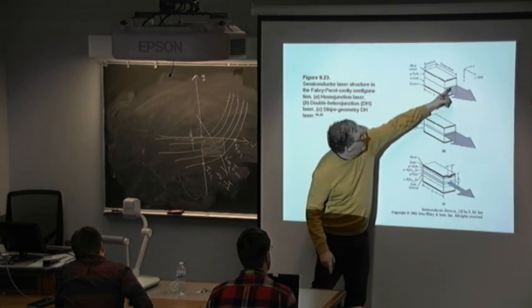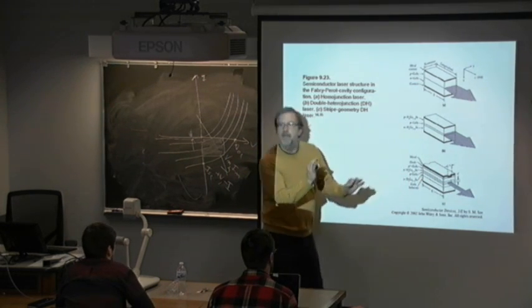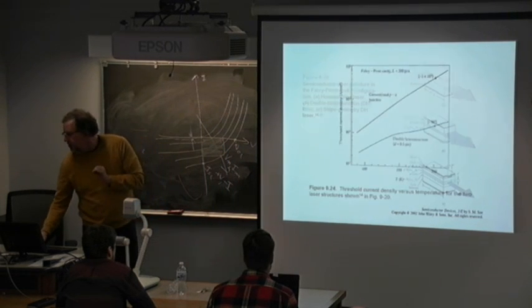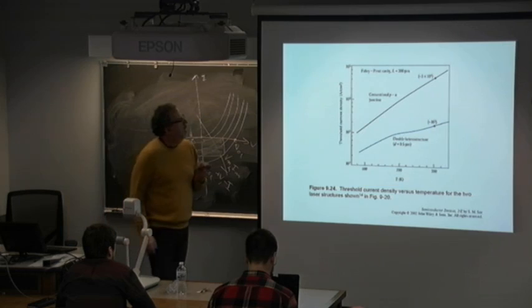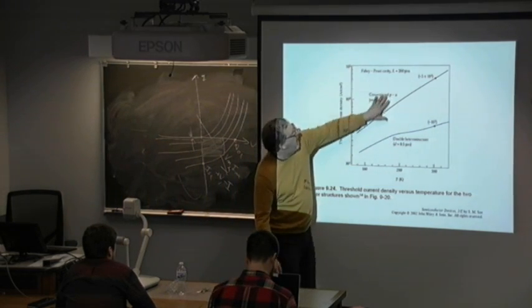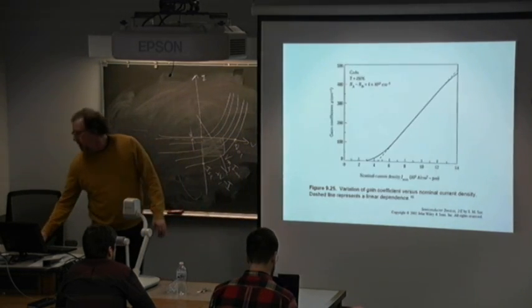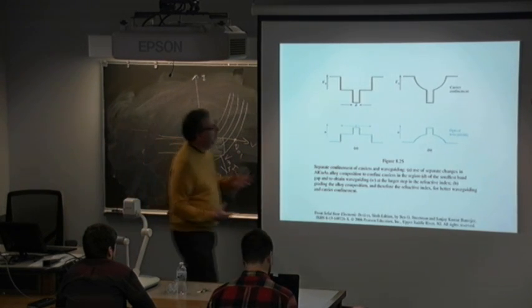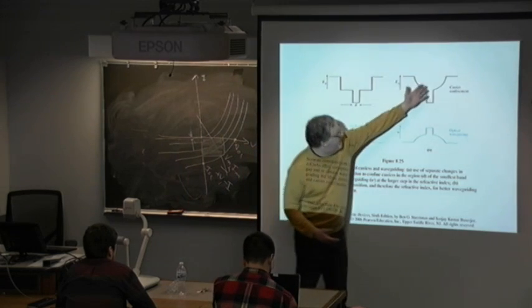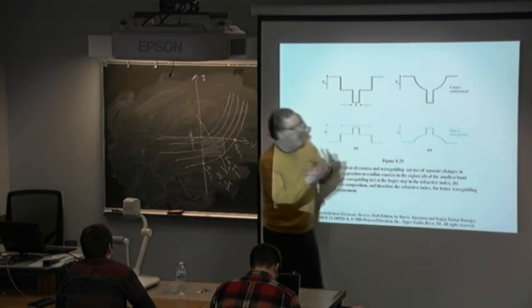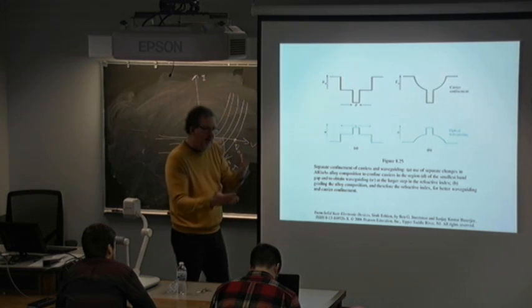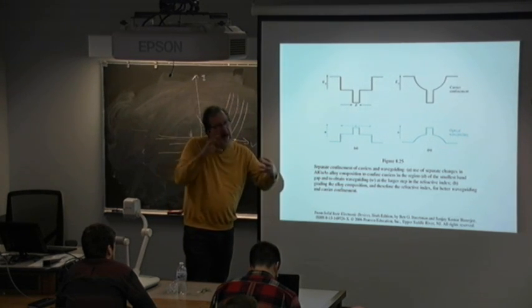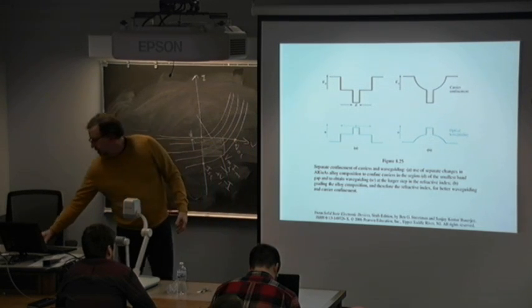But here I can do shape engineering of the beam coming out. And so therefore it's easier to focus and launch in, more power. And here I can get more power out, and so forth. But to get to the really more complicated, I'm going to do carrier confinement and optical waveguiding. I've got to consider both the carriers, the electrons and holes, but I also have to consider the photons being waveguided in the laser.